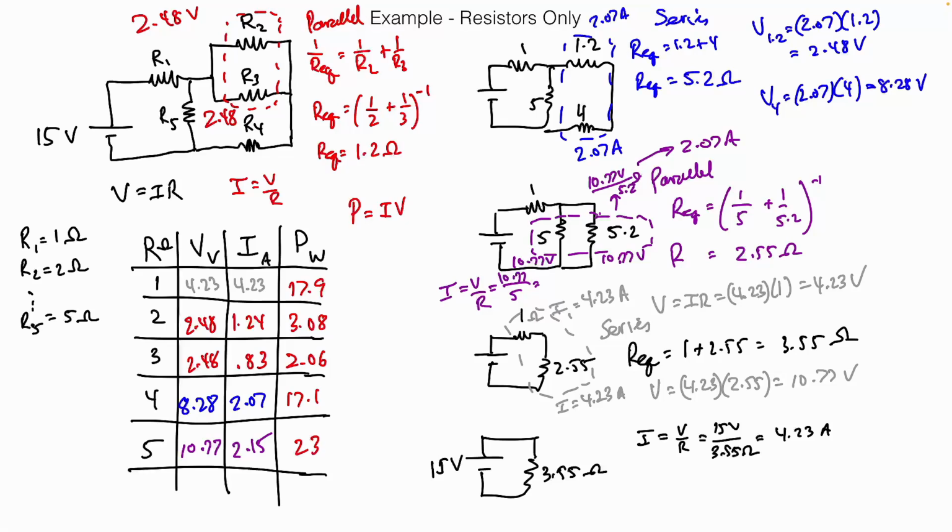The voltages don't add up unless we're really careful. The 8.28 is those two numbers put together, isn't it? It's voltages that split and then come back together again. So to get it right, we'd have to go through and it gets weird. Same thing with the currents because of the splitting and recombinations. The current through 2 and 3 splits up after 1 and 5 and then recombines before it comes back to 4.